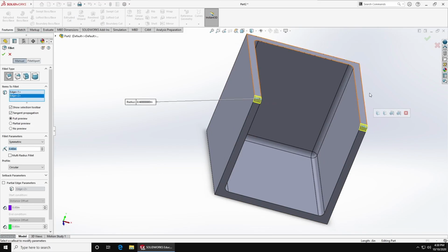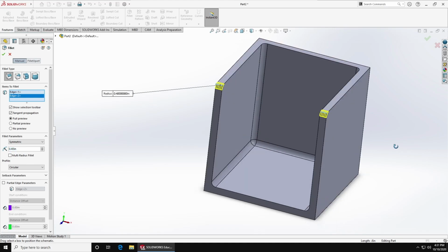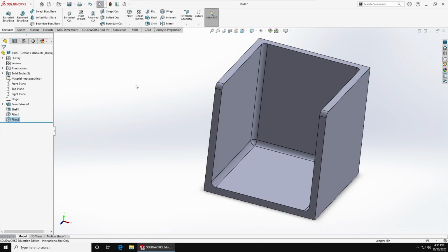One nice thing about fillets is that you can affect multiple disconnected things with a single use of the fillet feature. As we can see, I've rounded both of the corners off with just one application of the fillet tool. Additionally, we can see that fillets applied to angles above 180 degrees remove material, effectively sanding down the edges of the shape. In general, you're going to want one fillet feature per specified fillet radius on whatever drawings you're working on.